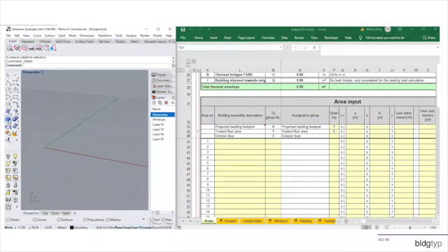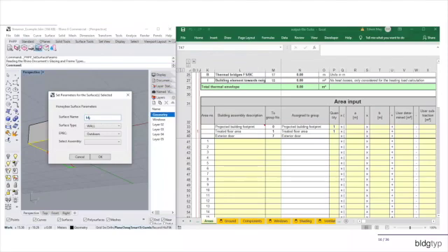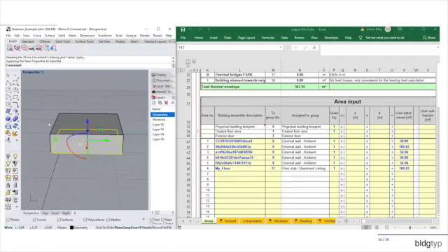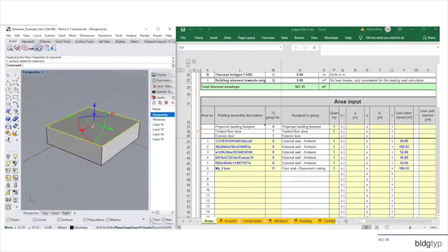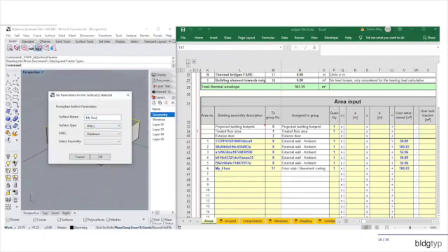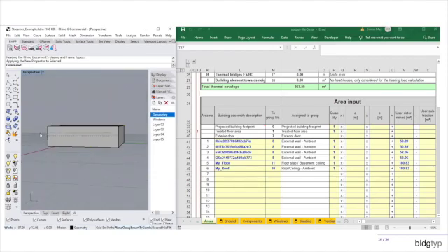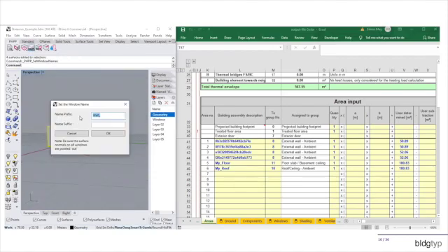So what does all that mean? Well, what it means is that once we've built out the connections, once we use our Rhino model and our Grasshopper toolkit to build up our pipeline, what we end up with is a really flexible data stream where the geometric and parametric data, which is encoded into our Rhino model, is going to stream through in real time into our PHPP model. As you can see here, if we take a super simple box model geometry and its PHPP representation, and we really quickly build up the geometry, as soon as we have a valid Energy Plus model, which basically means as soon as we have a floor, the PHPP updates automatically.